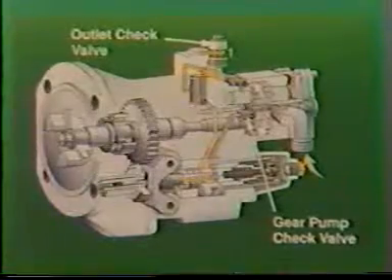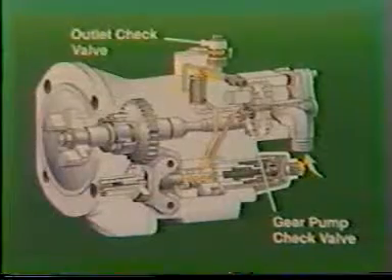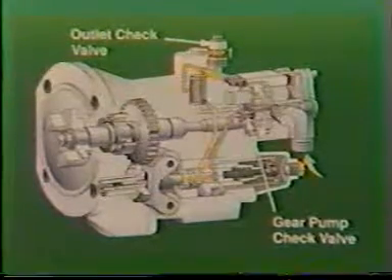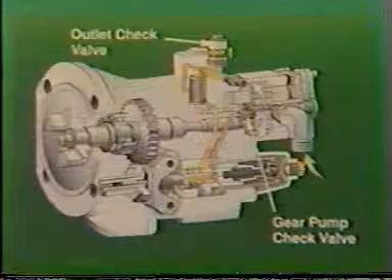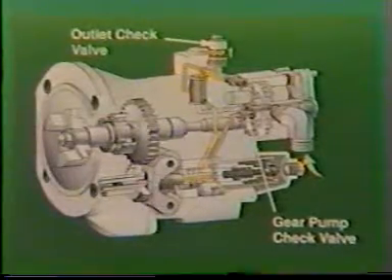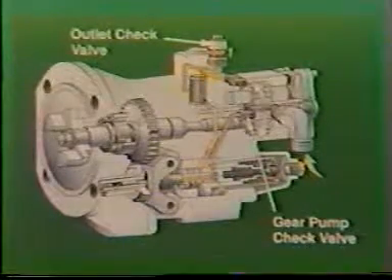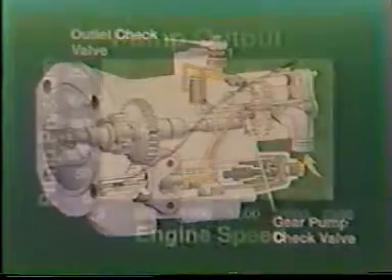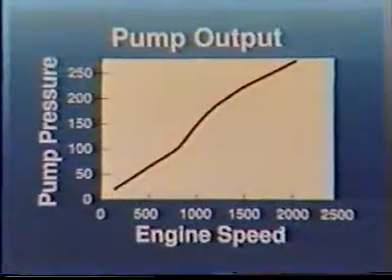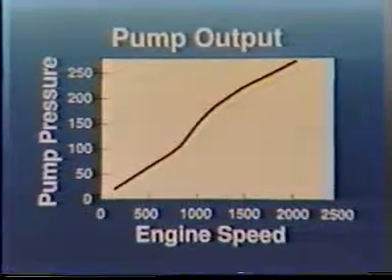The regulated flow output from the gear pump is directed to the PT pump outlet. A check valve in the outlet port controls backflow when the engine is not running. The PT pump does not contain throttling or AFC capabilities. The PT pump was selected because it provides excellent pressure characteristics over the complete RPM range.